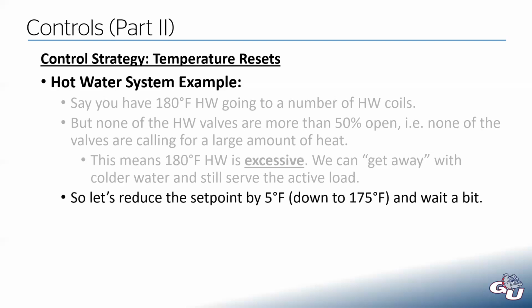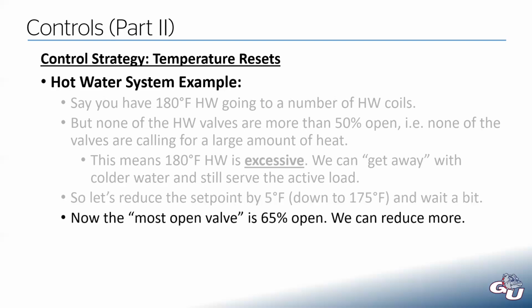So let's reduce our set point by 5 degrees, let's say, from 180 degrees down to 175-degree water. And then we wait and we see what the valves do. The valves are going to open a little bit more because we're sending them water that's not as warm, so now they need a little bit more flow. Now you look at the valves, and the most open valve is 65% open.